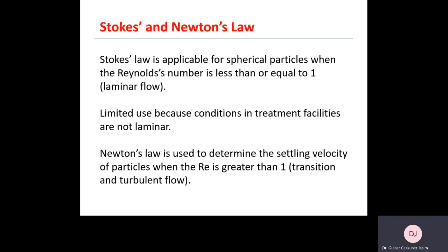Stokes' law has limited use because conditions in treatment facilities are not laminar most of the time. Newton's law is used to determine the settling velocity of particles when the Reynolds number is greater than 1, which corresponds to transition or turbulent flow.